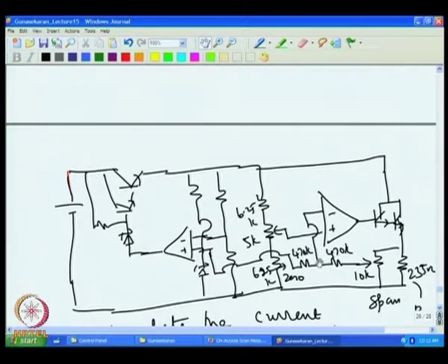So, if the resistance changes by 1 ohm here, then there will be a change in voltage, and half of that will appear here. So, it has to correct it back such that the current decreases again, so that the original voltage is retained.